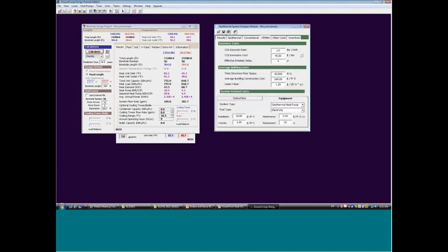Now, other costs are other things that we can consider in our life cycle analysis. We have CO2 emissions. So I'm going to leave this at a 1.0. This is sort of an intermediate index for clean electricity. If you have a coal-fired power plant that's generating all your electricity, the CO2 emissions are closer to 2 pounds for each kilowatt hour generated. If you're using a lot of hydro, very clean nuclear, et cetera, this could be as low as, theoretically, 0. So 1's kind of a middle ground. So I'll leave it at 1 pound per kilowatt hour.